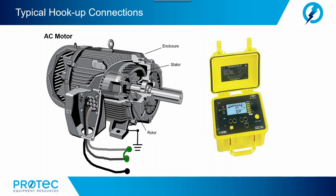Now, when testing all phases simultaneously, only the insulation to ground is tested and no test is made of the phase-to-phase insulation. The phase-to-phase insulation is tested only when one phase is energized and the other phases are grounded.